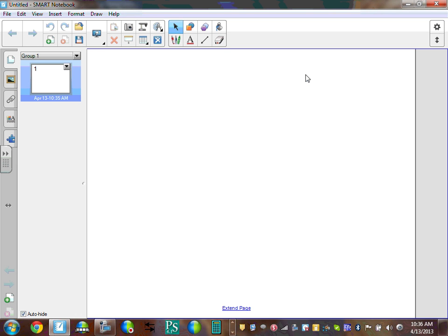In a smaller system, guys, an automatic transfer switch and manual transfer switch, 4-pole. In a bigger system, you talk about 4-pole circuit breakers, power circuit breakers, 4-pole, if you are to have a separately derived system. Typically, they don't have a separately derived system, so you have 3-pole circuit breakers, a non-separately derived system. If you have parallel switchgear, 3-pole circuit breakers, and the neutral is bonded for the whole system. So does it make sense? So that's basically that one.